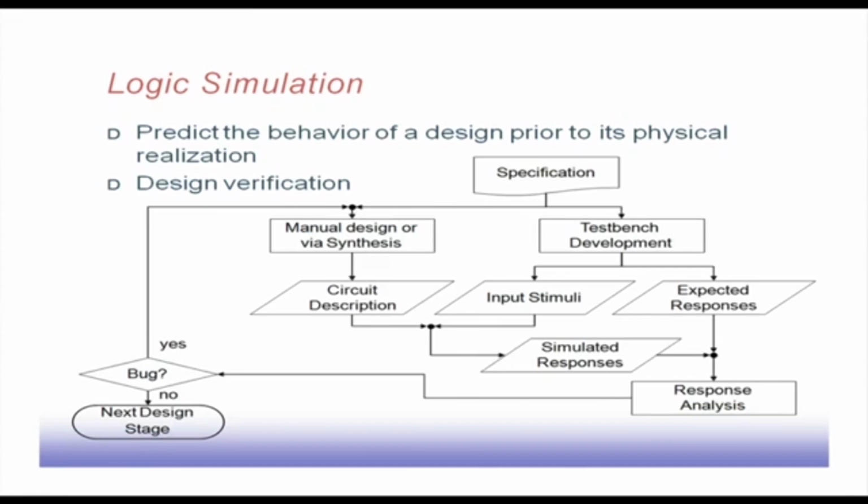So, this logic simulation problem predicts the behavior of a design prior to its physical realization. This is basically the problem of design verification. A specification is there, and it goes into manual design or via synthesis. It may be manual design or maybe by a synthesis tool, and it gives the circuit description.